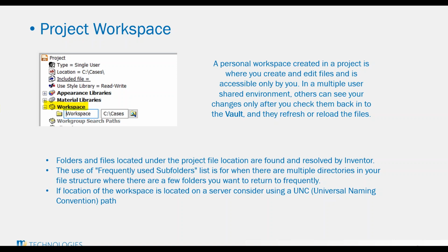If you choose to have it on the network, you are taking on the risk that you are saving across the network. We do recommend you having it local. That way you're saving to a local drive, and then at the end of the day, through maybe a copy and paste, you can move information onto your server. In some cases, we've seen information packets being dropped. There's no rhyme or reason around that. It could be network traffic or a network hiccup. But if you happen to lose packets of data, that file is more likely going to be corrupted and unopenable. Just be aware of that.